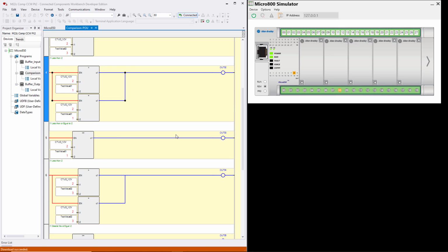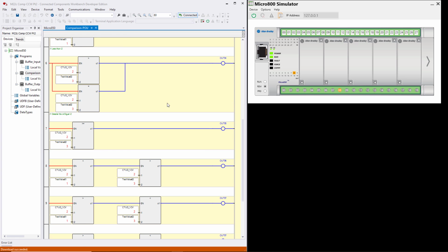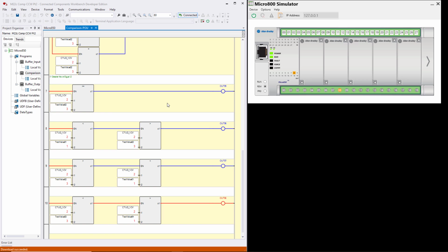I just threw in some rungs of logic that you were going to see a little later on. In other words, we had a section on equal and not equal and adding those in parallel with less than or greater than. Now if we slip on down a little lower here, this was some code that was in the earlier part of this lab. I'm going to clear by toggling input 27 so you can see that all 3 of these are false.